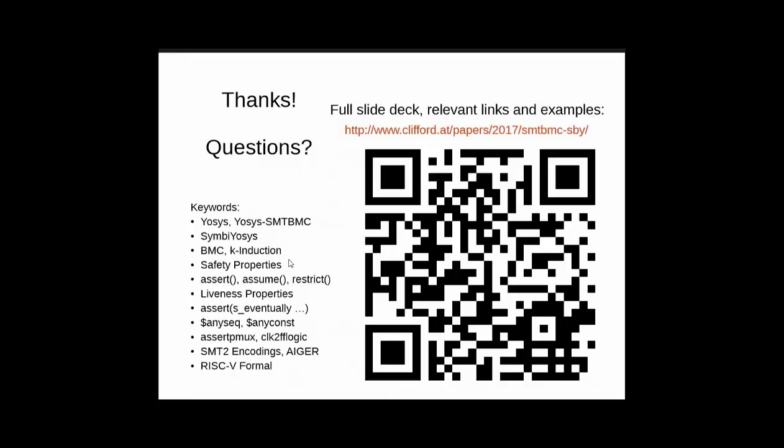Yeah, the Unix return code of SymbiYosys is usually 0 when it passes and 1 when it times out or fails. And with the expect statement, you can say what kind of things you expect. And when you write presentation slides with an example that's supposed to fail, and then you have a makefile for that, so you can go there and download all the examples and then run make in the makefile, I don't want the makefile to stop because this thing failed. So I tell it, expect it to fail, and then it will return 0. Right. Thank you.